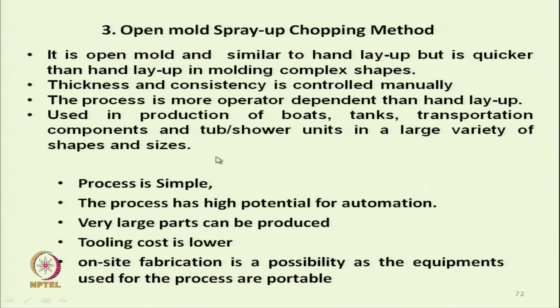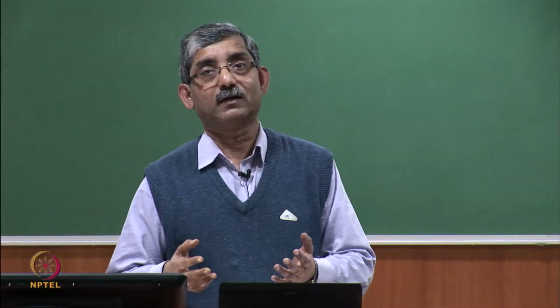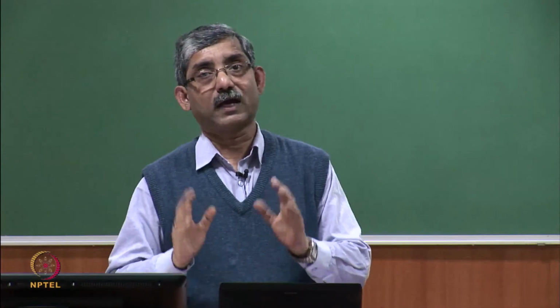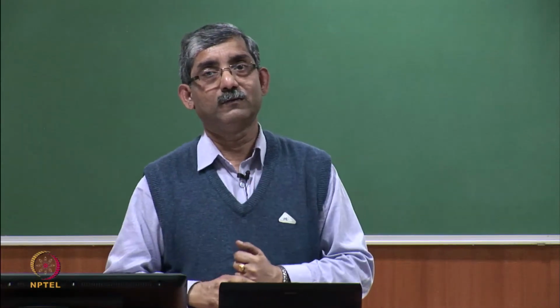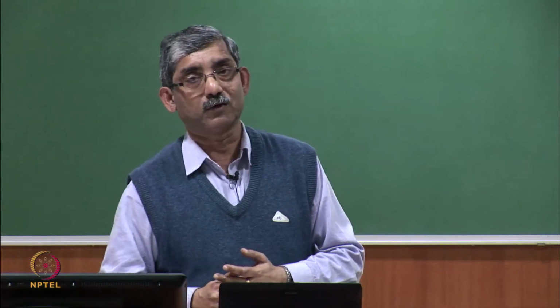The main advantages are that the process is simple, it has high potential for automation, very large parts can be produced, and tooling cost is lower. On-site fabrication is more important: if we want to fabricate some composite on site, we can do that by using the open mold spray up chopping method.